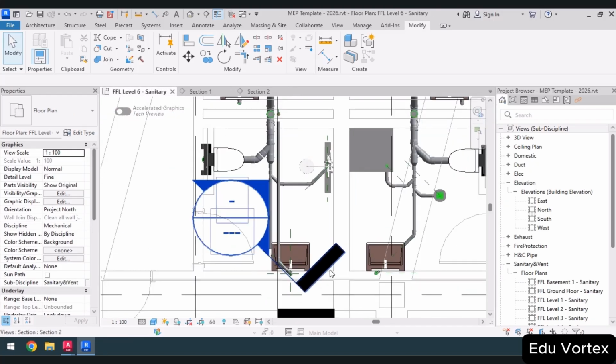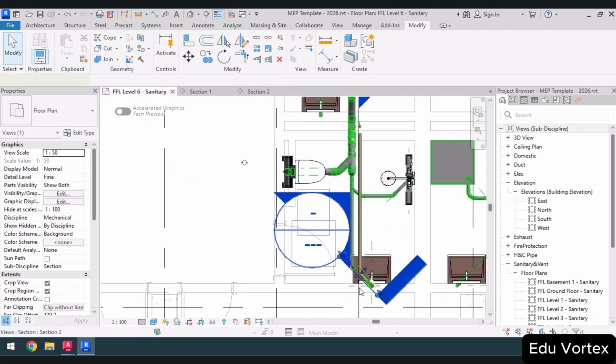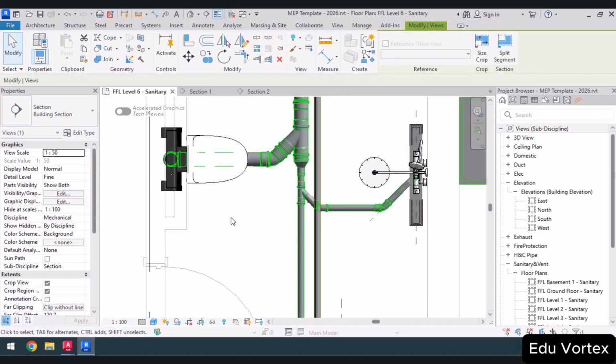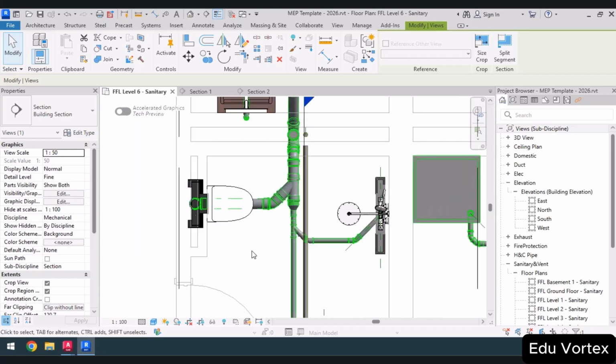Next, I will move to the vents related to our western restroom. For this service, I need to bring the vent pipe close to the nearest wall and then go up through that wall so that I can connect it. The nearest wall can be either here or on this side, it doesn't matter. The pipe will come through here into the wall and go up before connecting here.